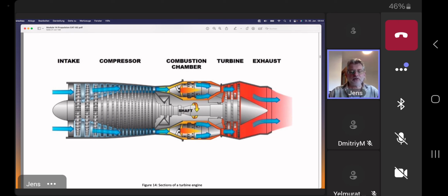This is a disadvantage of the radial compressor. The radial compressor is not able to consume as much air as an axial compressor because we have to re-guide the air since it's radial, and so it does not make sense to have more than 2 stages after another. Otherwise, you have loss in energy because you have to redirect the air.